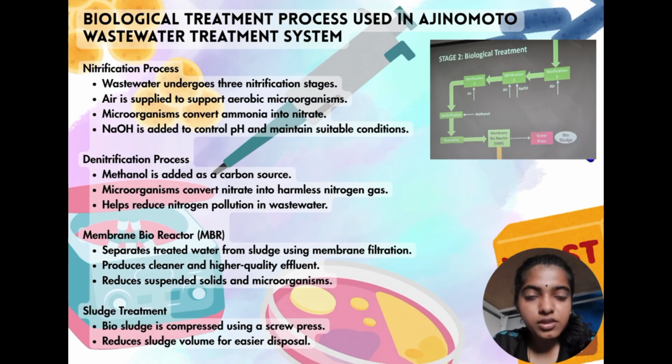In this stage, methanol is added as a carbon source, where microorganisms convert nitrate into nitrogen gas, which helps reduce nitrogen pollution before the water is discharged into the environment. And then the wastewater undergoes the reaeration process, where oxygen or air is supplied to the tank to increase dissolved oxygen levels and support further biological treatment.